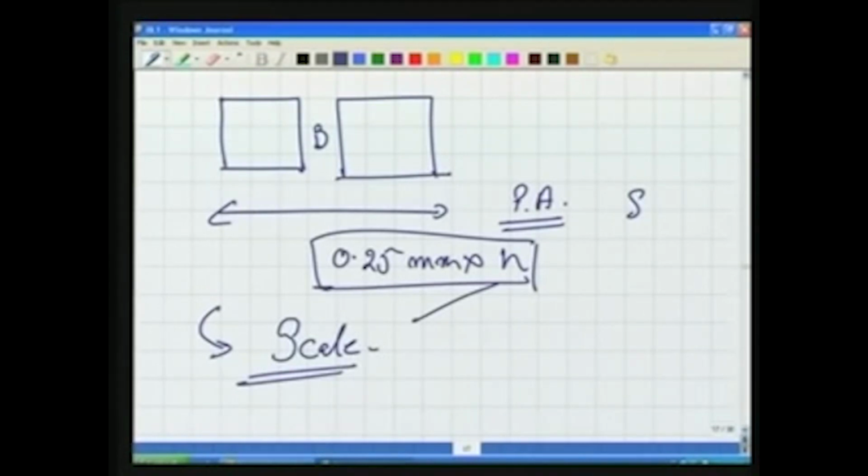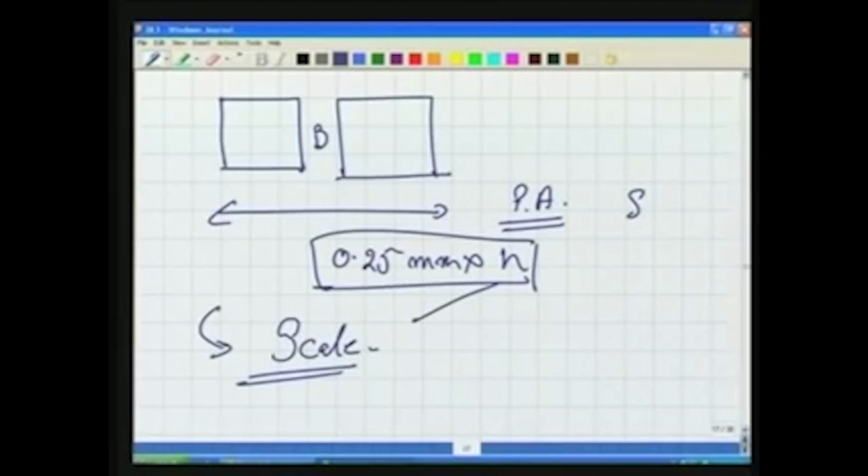Okay? Having seen all these things, we have seen some principles of surveying. For example, in any mapping exercise, we must do the reconnaissance, number one. Number two, we should establish a control network, because we want to work always from whole to part. And we fix the control network in our area first.